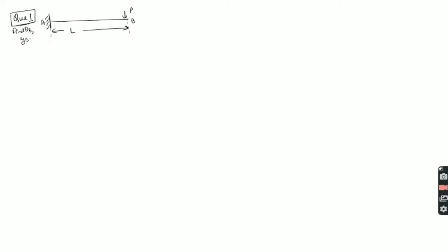Always remember, whenever you are solving any such question, the first step should be to have an idea about the elastic curve or the deflected shape of this particular beam, right? Because we need tangents at different points, first I will draw the elastic curve. As you know, this is a cantilever beam, so it will deflect like this. This black line here is representing the deflected shape or the elastic curve of this beam, right?